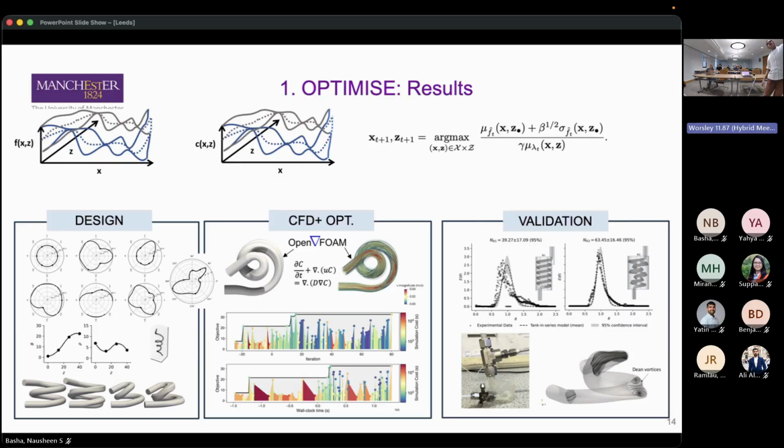And then finally, we get to a shape that looks like this. And we visualize that shape with a fluid dynamics model. And then we finally see formation of Dean vortices that you didn't see with a vanilla coil that is just simply coiled like this. So that confirms that the Dean vortices are occurring, but now we want to see, can we validate it again with experiments so we can see a good plug flow performance.